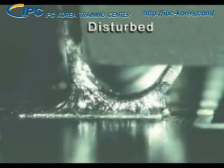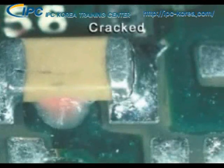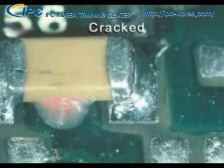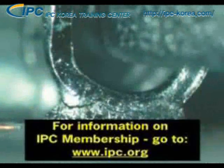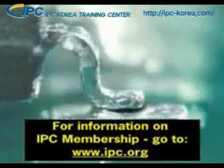A disturbed solder joint is characterized by a gray, porous appearance with stress lines from movement of the solder while solidifying. This is what a fractured or cracked solder joint looks like on our 3 types of components. A cracked solder joint will not allow the electronic signal to flow. That's why this condition is a defect.